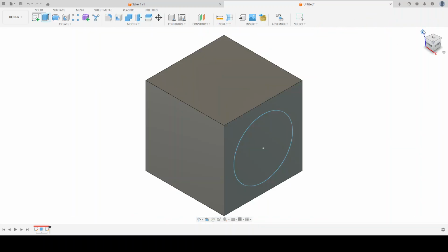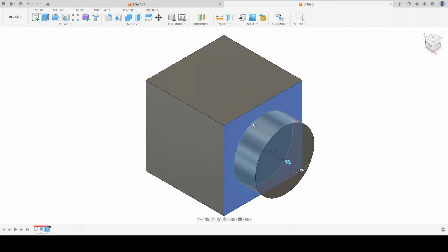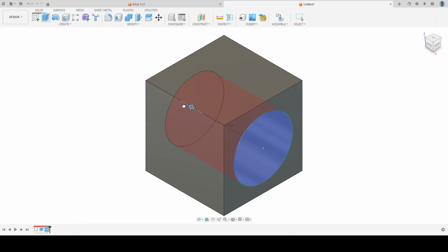And now we'll go ahead and talk about the other types of operations. So first and foremost, if we drag outside of the part, or extrude it outside, you have the operation called join. What that does is add material, but it's going to consider all of that one single body.